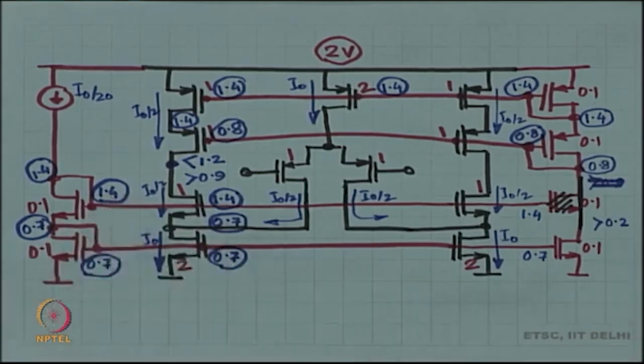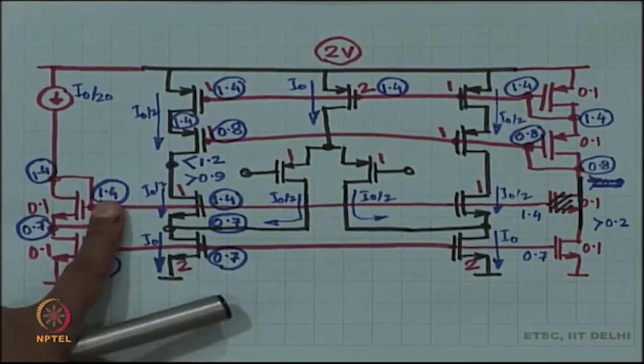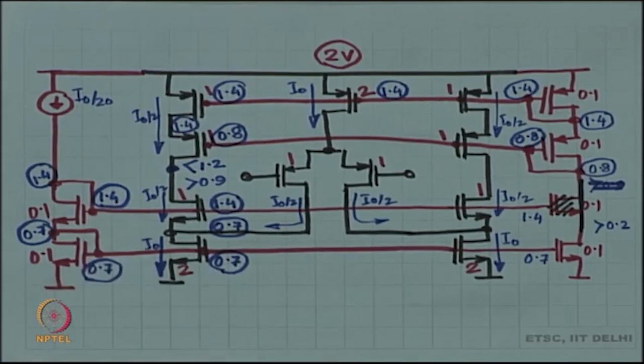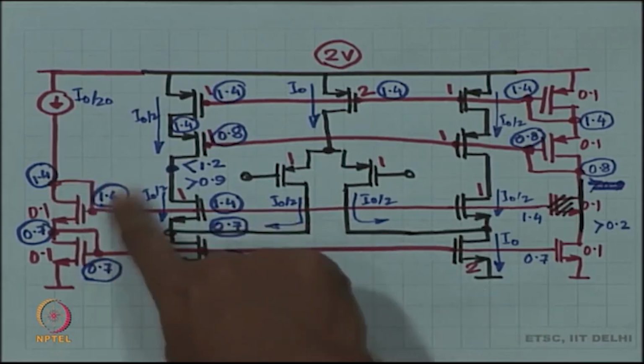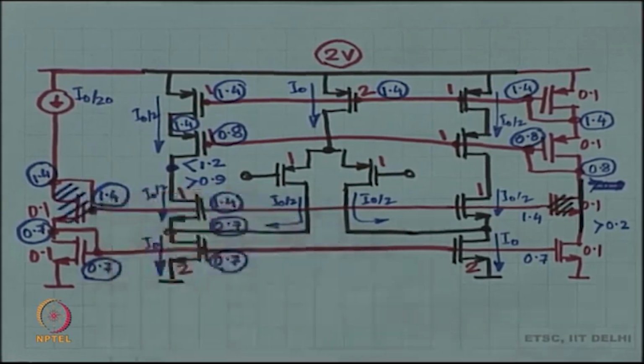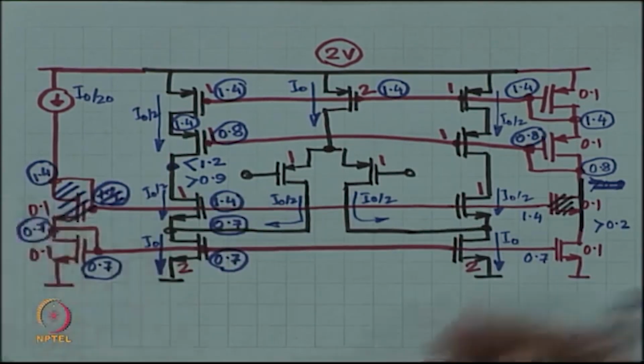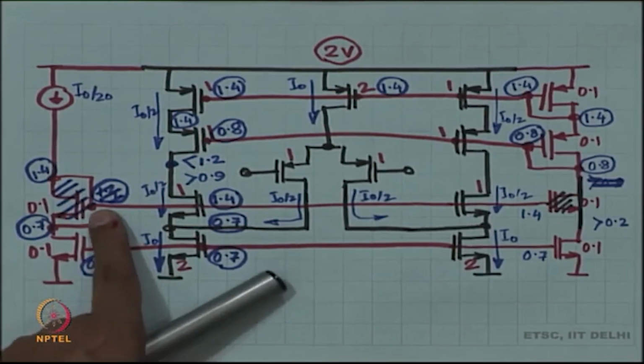Why do you need 1.4 over here? This voltage can easily be lower. So, let us not do 1.4 volts, let us make sure that somehow, not this way, some other way. We are going to make sure that this voltage is not 1.4, we have to be creative. Remember, we did all those optimal current sources and current mirrors and so on. So, this one is no good.